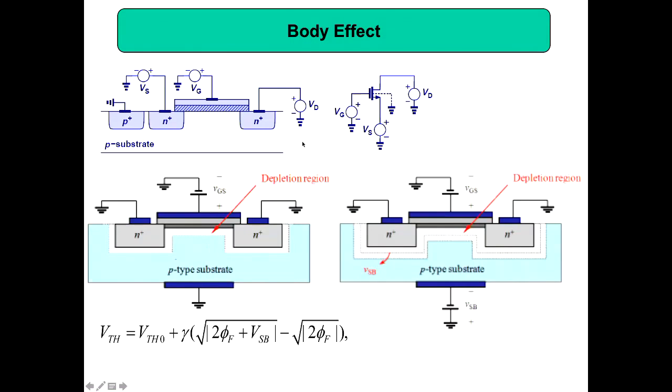When you see this notation, and then another one without the notation, you might ask, why do we need to ground it? We need to ground the substrate in the design. Definitely we can't leave it floating. There will be maybe some leakage current. So in the original chip design, they will ground it. Then the question is, when you ground it, people in the foundry might ask, we are grounding the body, is there any effect? Definitely there is an effect. People already found out your threshold voltage will increase slightly.